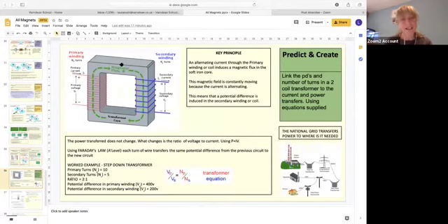Here, the magnetic field that is being set up by this, because this is an iron core, it's not a magnet, it becomes magnetic. This magnetic field that is being set up by my electrical current here is basically stopping and starting, isn't it? It's going backwards and forwards. There's movement in this magnetic field line. So this then sets up an induced potential on this one here, and my current can go through.